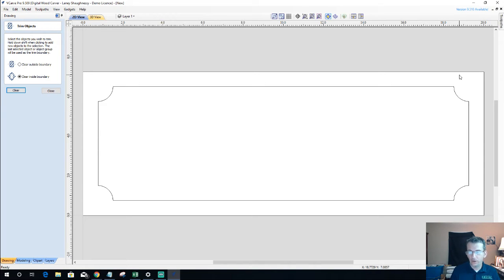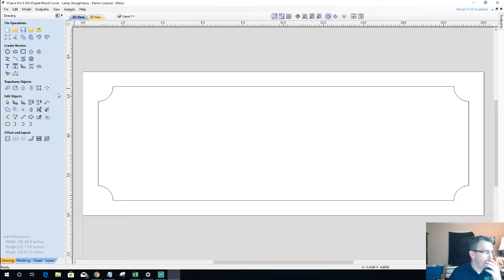So there are three options for getting to that same point. You've got your rectangle tool, which is very simple: you choose the corner radius, tell it what size radius, and boom, you're done. Or you can subtract one shape from another, or trim one shape around another. For those of you who are new and just joining, I wanted to stress that there's more than one way to get to an end result.